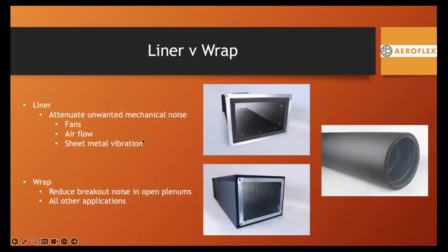When to wrap and when to line a duct. When does an owner, engineer, or acoustic consultant determine that? For liner, it usually is driven by the need for acoustics to attenuate or reduce unwanted mechanical noise. And that could be fan noise, airflow, and also sheet metal vibration on ductwork that's going over sensitive spaces in a building. And the liner usually falls under the scope of work of the mechanical contractor, the sheet metal contractor, or the contracted duct fabricator.